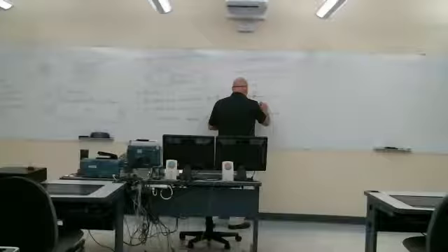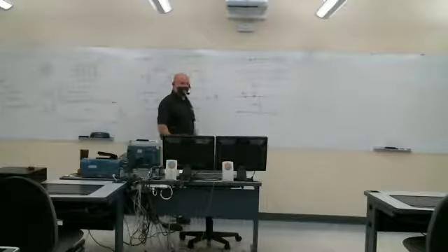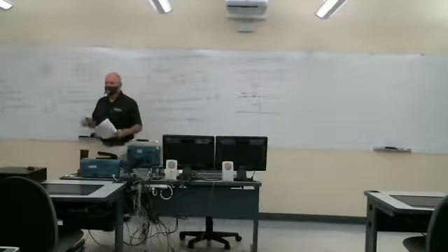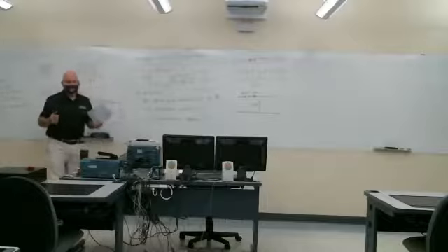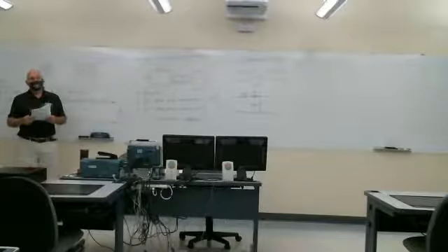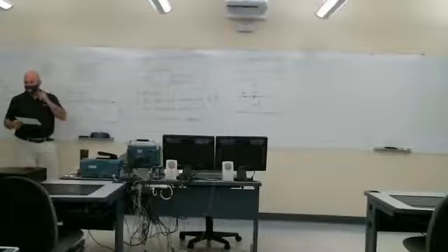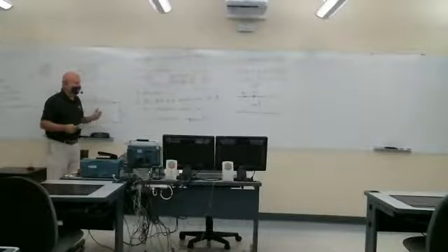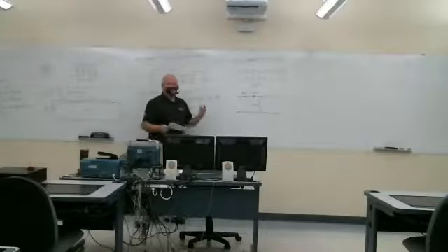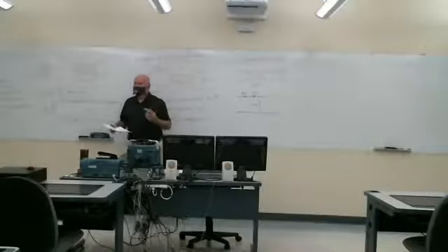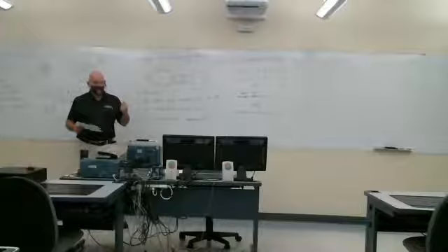There can also be what's called a leakage current between the two conductors. You know, a small amount of current, even though it's an insulating material between them, there can be a very small amount of current flowing through that insulating material between the two conductors. And we model that as, here G is our symbol for conductance. So we model that as a conductor.